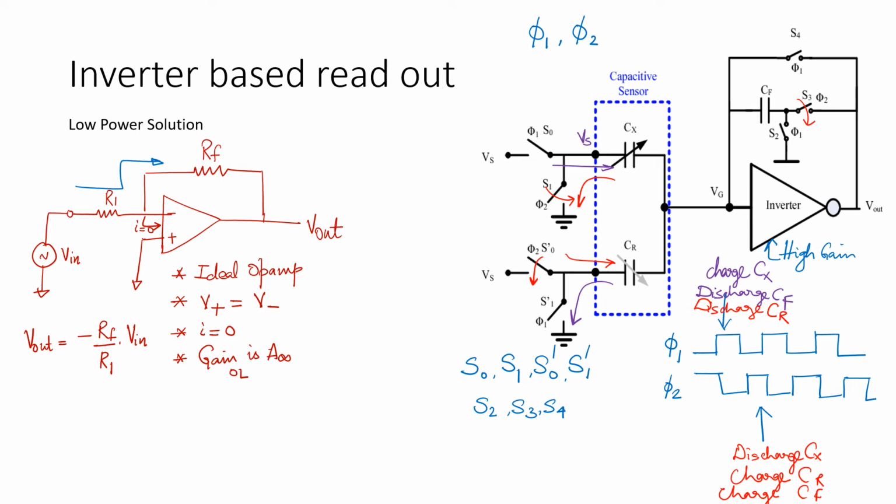This is a differential capacitor sensor where you are having one to detect the change and the other to nullify the experimental or the environmental characteristics of the sensing environment. So what will happen is, the value of Cx will come out, and the value of Cr when Cx is not present will come. So your actual sensor signal will be delta C, which is the difference between Cx minus Cr. So this is your actual charged capacitance. Now with this understanding, we have understood the first half of the circuit.